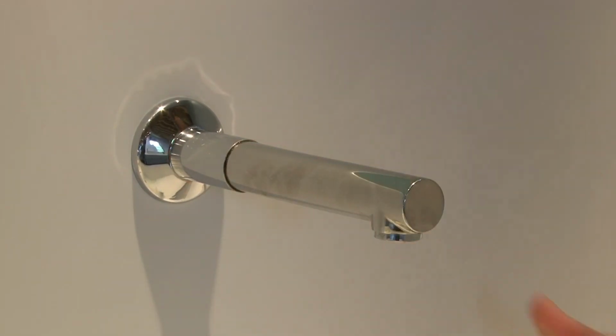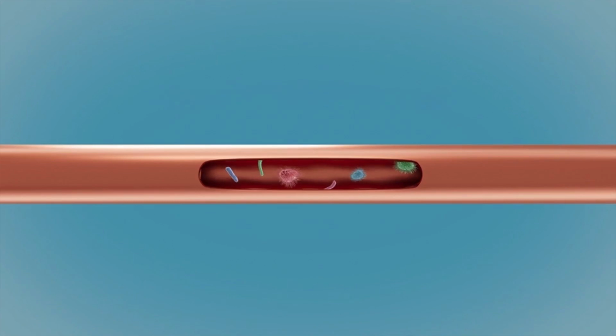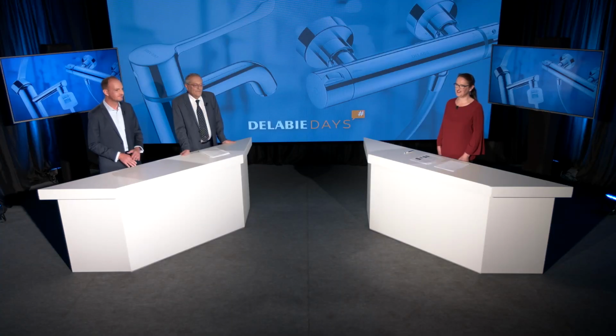Professor Hartmann has just reminded us how important it is to fight against water stagnation, and certain countries, Germany and the UK included, require the system to be flushed regularly. This is possible with our electronic taps that have an antibacterial duty flush, which activates automatically 24 hours after the last use. So the valve opens automatically for 1 minute to flush the pipework and rinse the mixer to prevent water stagnation. You really do have a lot of solutions. No non-return valves, removable mixers, automatic duty flush. The list is long. What other solutions does Delabie offer?